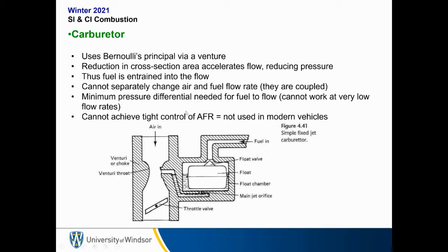So generally, carburetors are not used in modern vehicles. They're still used on small internal combustion engines that might be used for a lawnmower, a string trimmer, or what might be more commonly referred to as a weed whacker. Snow blowers will also use carburetors, although some snow blowers now use fuel injectors as well. But generally only small engines, and only single cylinder engines, use carburetors nowadays.